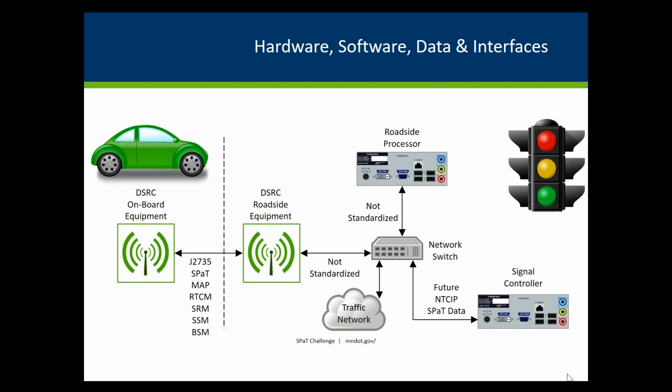So SAE, the Society of Automotive Engineers, has a J2735 that says what's in all those messages. And so you should be able to get anybody's brand of DSRC. It should be able to send those messages to anybody else's, and it'll work. But the back end, the other side of the DSRC, is not standardized. So that's going to make it a little more complicated.